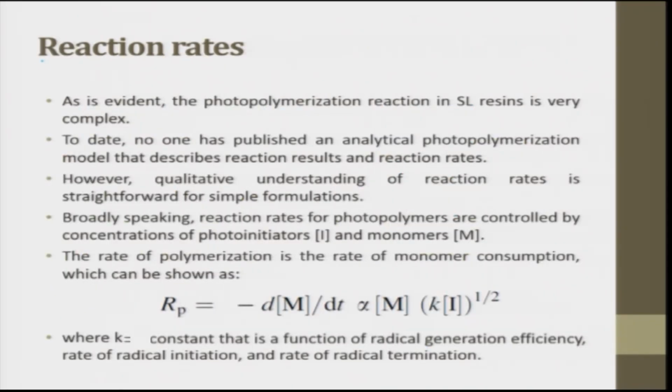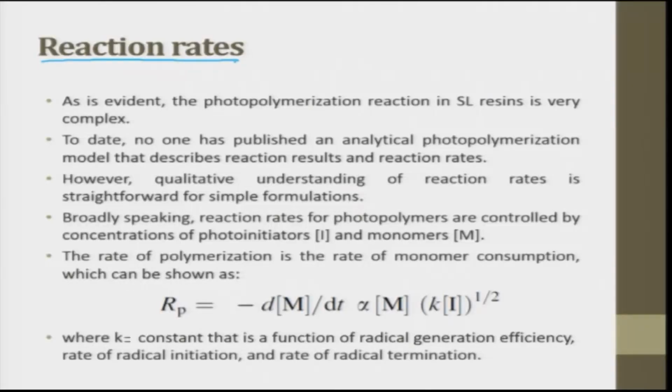The important property of the entire photopolymerization is the reaction rate. Because how quickly does the reaction happen such that the liquid is converted into a solid. You can make it in one shot, liquid to solid, or liquid, viscoelastic nature and then solid. Suppose if this takes a slow duration of time, the best part is going to be between spots, it is going to gel and form a line very well. If it is instantaneously curing, you might not get the gelation very well, and when you talk between layer to layer, again there can be a possibility of delamination. So, in that case reaction rate plays a very important role.